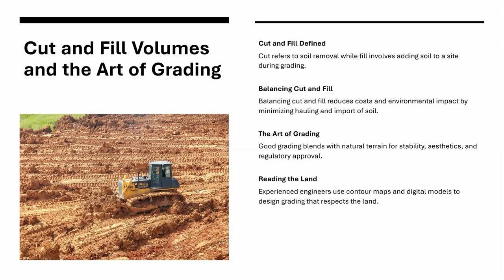A site that completely ignores natural terrain, carving rigid artificial slopes, may work on paper, but it fails in reality, with erosion, drainage complaints, and plenty of community opposition. This is why experienced engineers and surveyors often talk about reading the land. They use contours, TINs, and DEMs not just for calculation, but as guides to design grading that works within the terrain instead of against it.